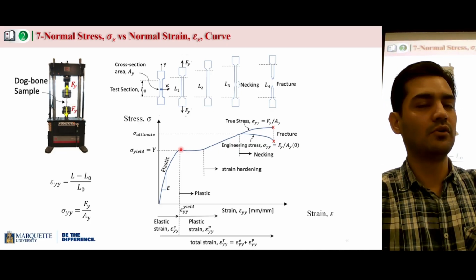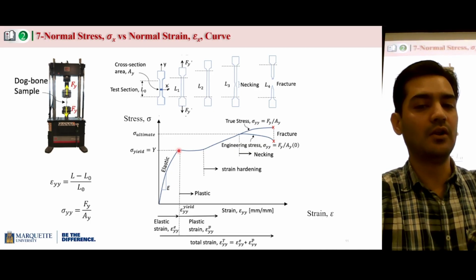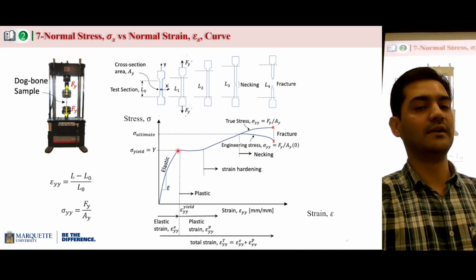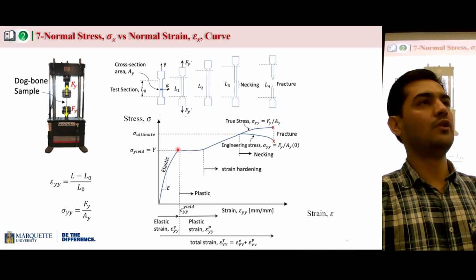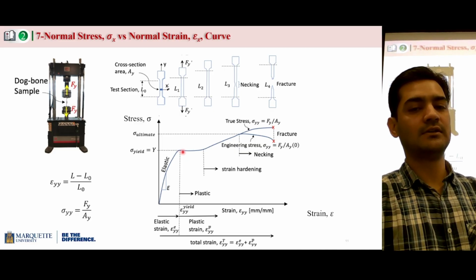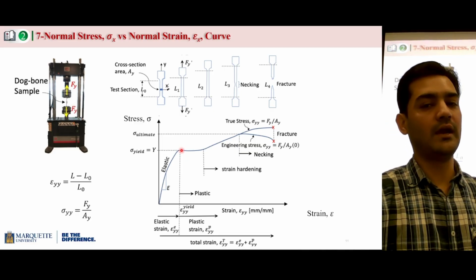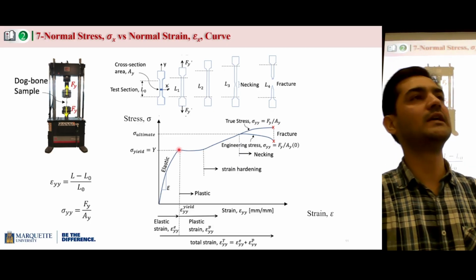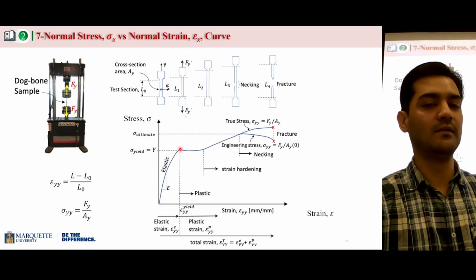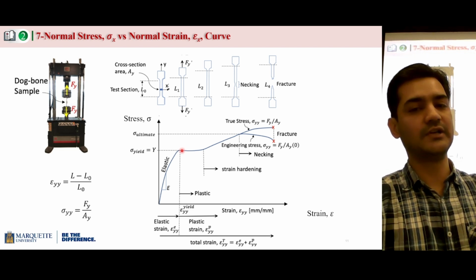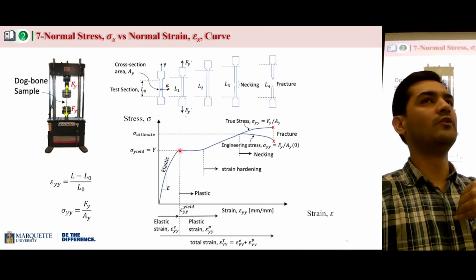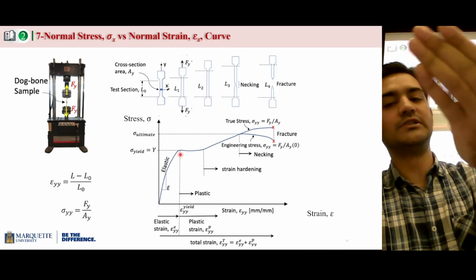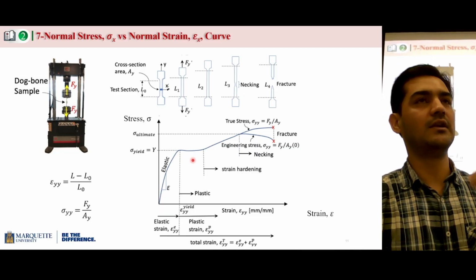So we'll make sure that the stresses are below the yield stress. So that's the yield stress. That's a very important point. So we'll not exceed the forces to a point where you will have stresses higher than the yield stress. So yield stress is a material property. For every material, you have a specific yield stress, and we don't want forces to go beyond the yield stress, because then we'll have permanent deformation and we're going to have problems.